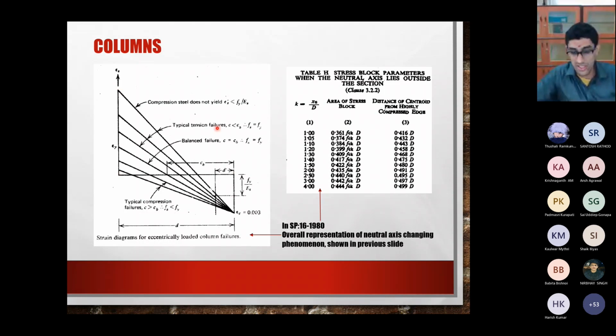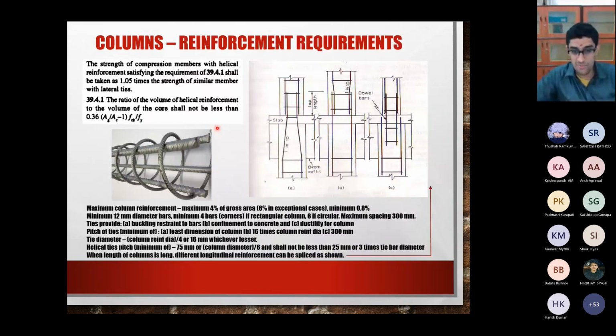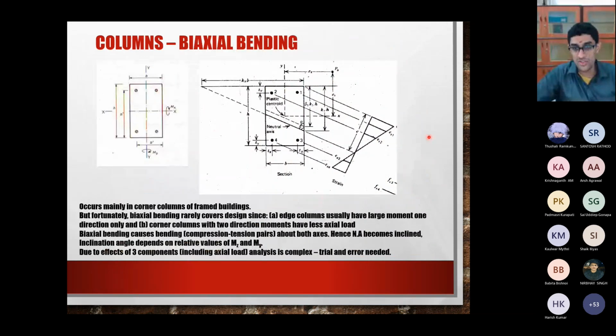Okay, so when you have biaxial bending, it will not be like that. You will have an orientation of stresses which is not aligned with this edge, and it's not aligned with this edge either. So the actual final stress distribution due to both Mz and My will be a resultant. When I say resultant, obviously you know that when you have x and y, two different forces, the resultant will be inclined. The same thing.